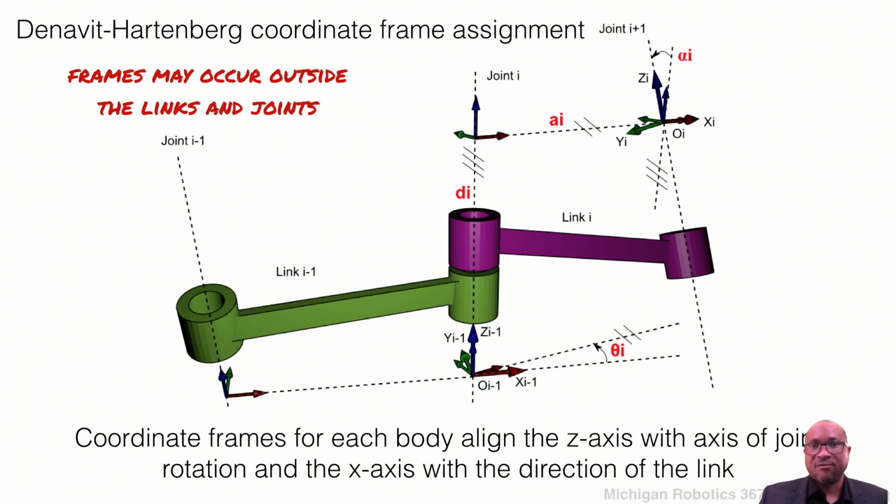We should note that if we use Denavit-Hartenberg notation, there's a frame assignment process that also has to happen. The z-axis is always going to be aligned with the joint axis, so now it's not going to be a separate z-axis for the joint that's different from our axis of movement. Those are going to be aligned. And so now we know what these z-axes are, and we have to attach frames to each of these z-axes for every joint. We have to do a frame assignment process. But once we do that, then DH will work nicely.